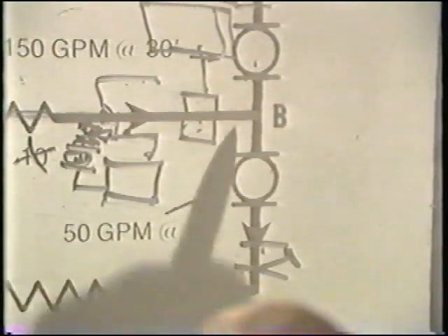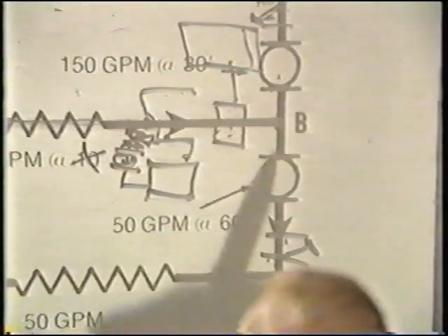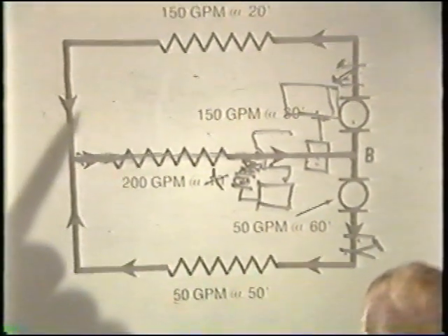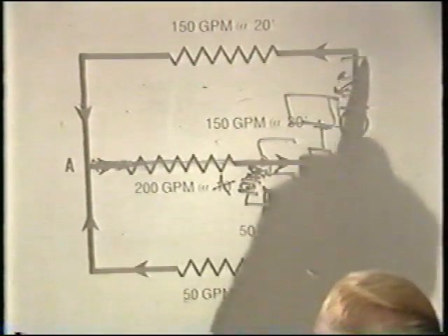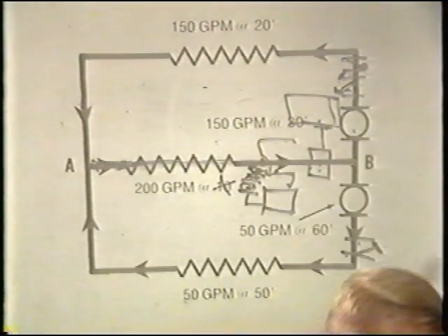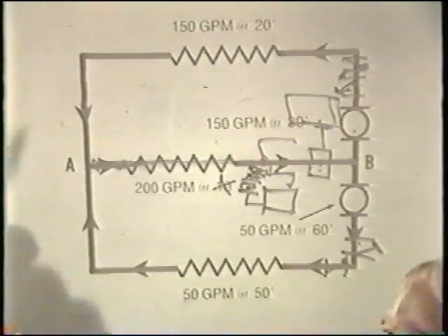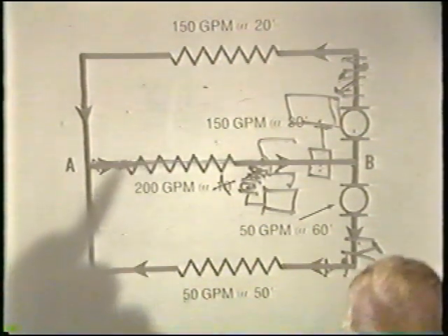This would eliminate again the change in head loss in the piping common to both zone pumps, which can cause difficulties and could cause the check valves at the discharge of each of these pumps to close, given a very substantial change.